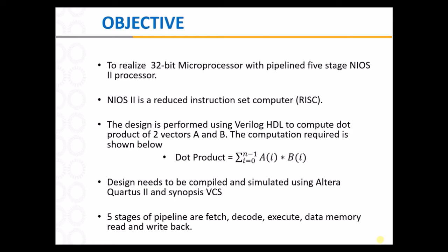The instruction set architecture of the NIOS II processor is classified as a general purpose register architecture, wherein there are 32 general purpose registers. All the NIOS II instructions are 32 bits long. In addition to the machine instructions that are executed directly by the processor, the NIOS II instruction set includes a number of pseudo instructions that can be used in assembly language programs. The assembler replaces each pseudo instruction by one or more machine instructions.